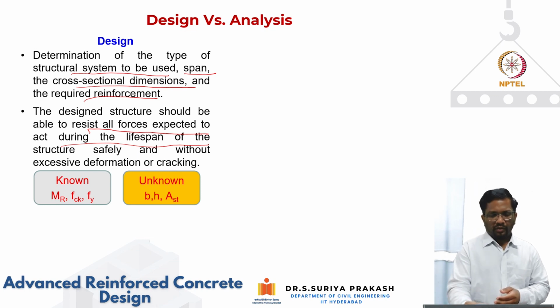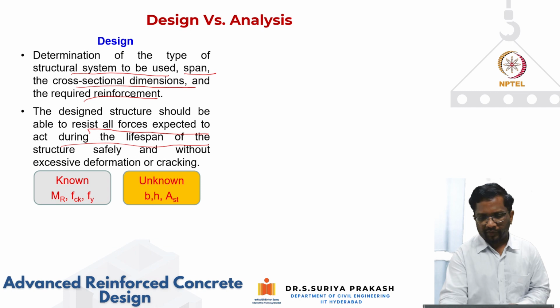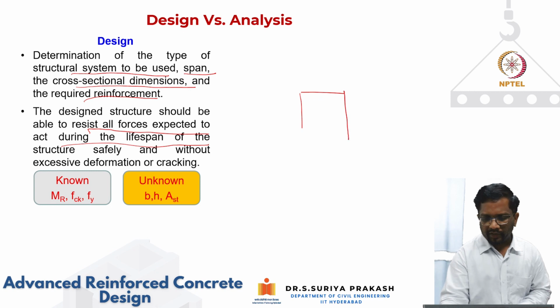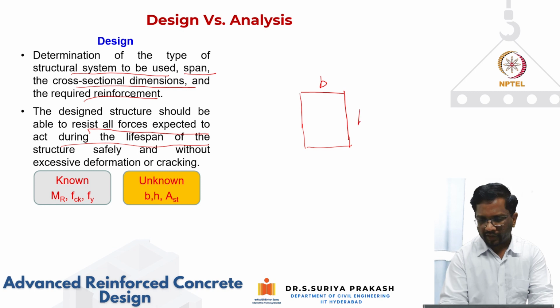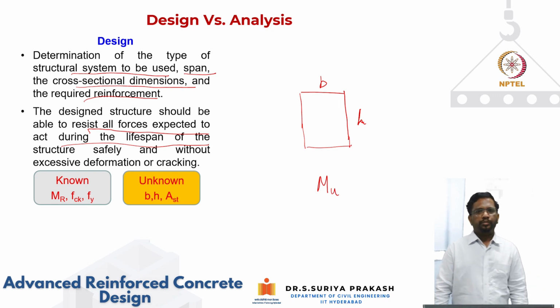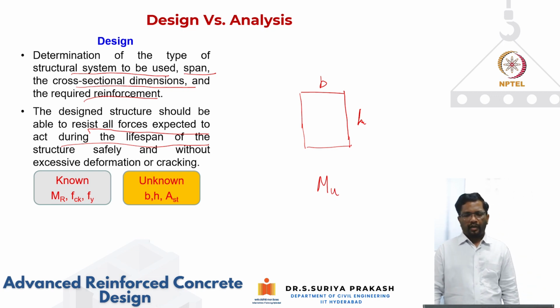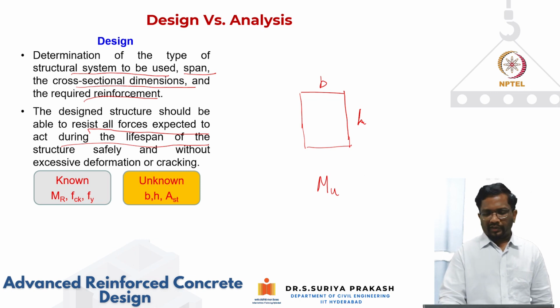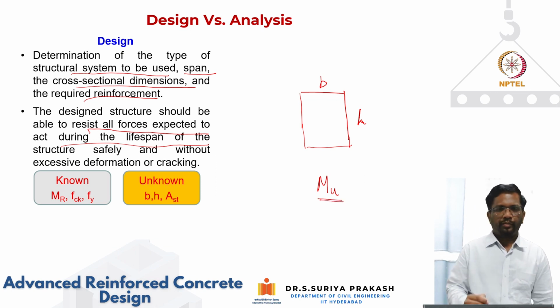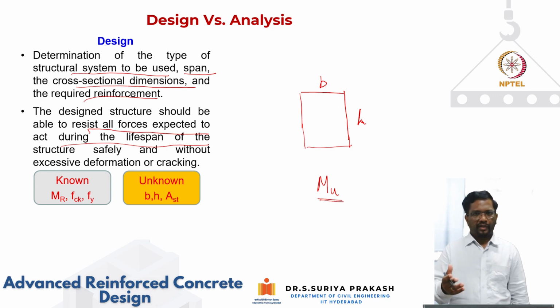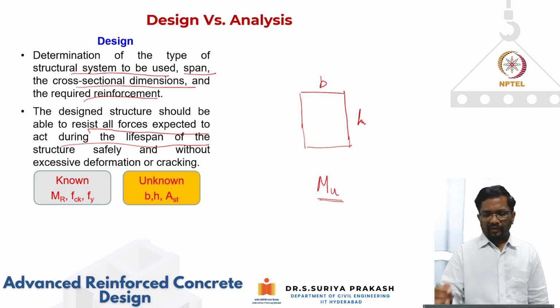Now, in flexure, for example, when I look at this kind of beam that we are talking about, let's say that I come up with these beam dimensions. Let's say this is B and H. I want to design this beam for a demand which is a bending moment of Mu. Usually, like I said, to get this bending moment Mu, first of all, I need to do structural analysis to determine this Mu.